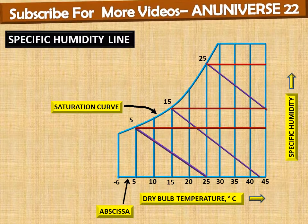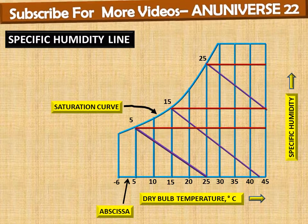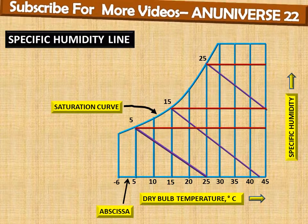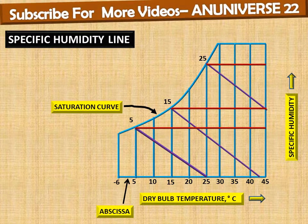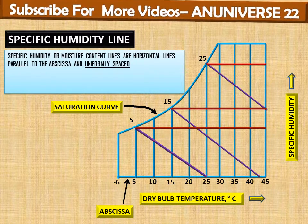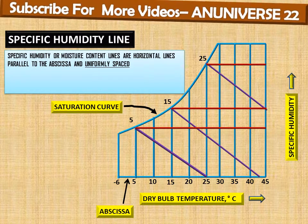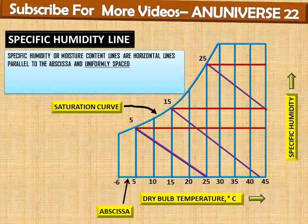Next is the specific humidity line. These lines are also known as moisture content lines. The specific humidity or moisture content lines are horizontal lines parallel to the abscissa, and these are uniformly spaced.